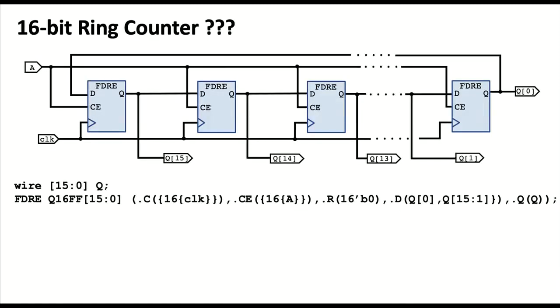Is this a good 6? What I'm doing here, instead of before where I had in here, is now I'm connecting Q0 to in. So this is my ring counter, right? No? What's wrong? They're all going to initialize to 0. Oh, darn. Okay, yeah. So the little problem here is all of these flip-flops are going to wake up with zeros, and that makes for a very dull ring counter, right?